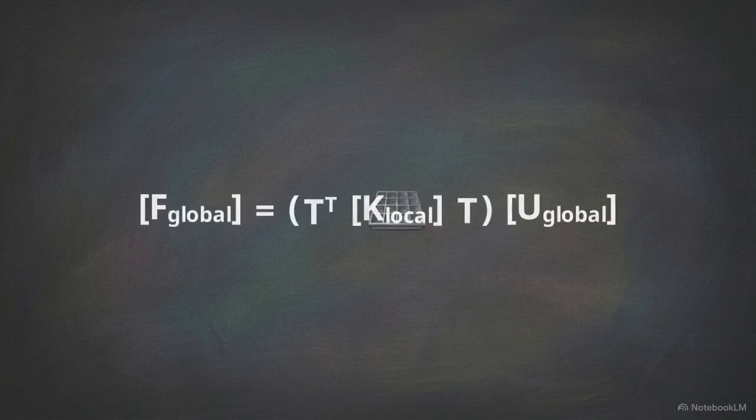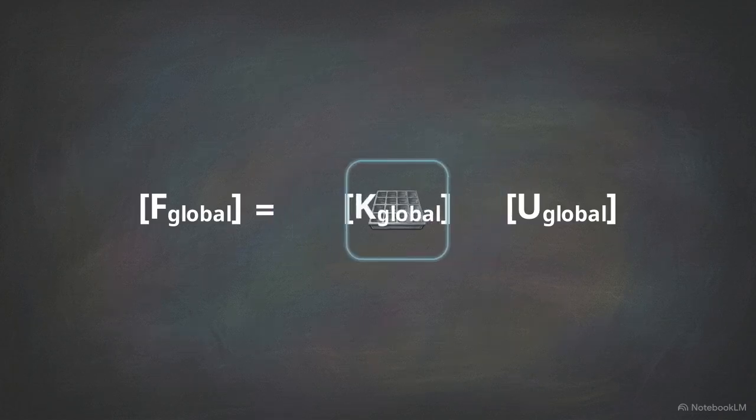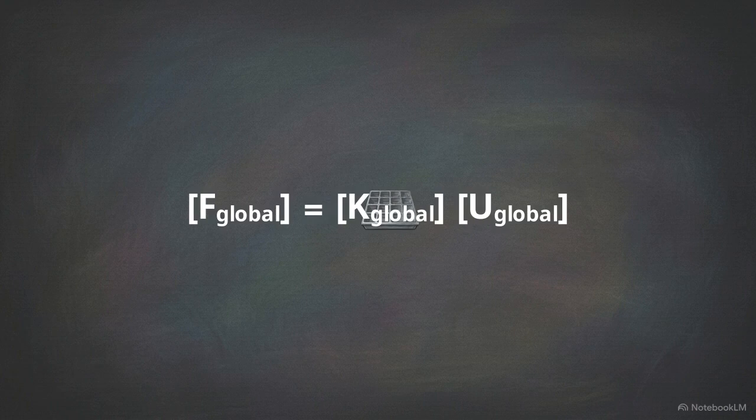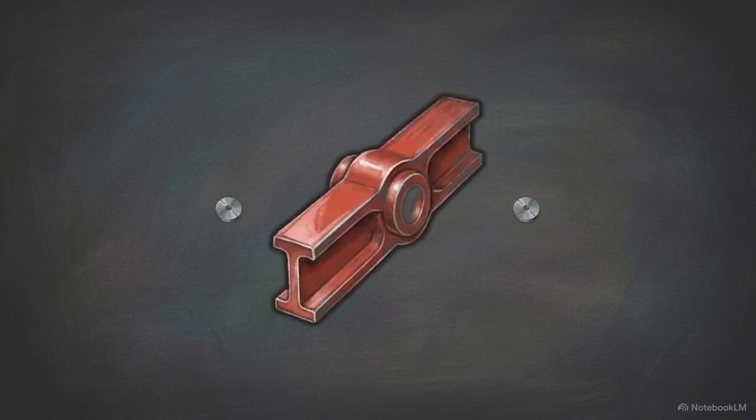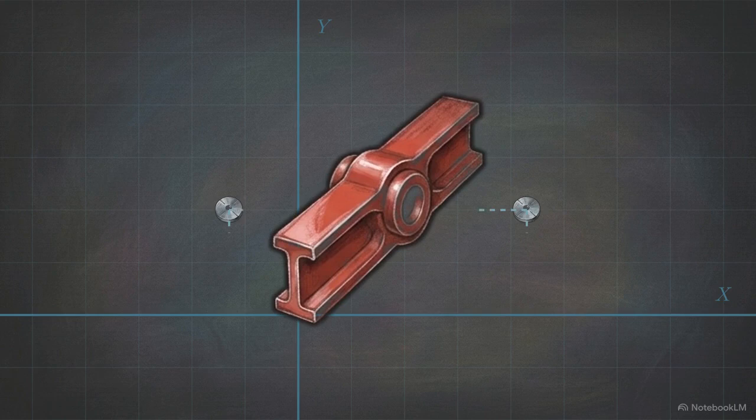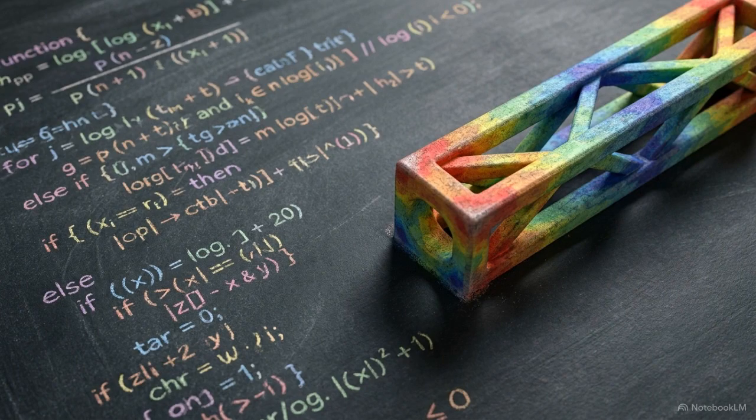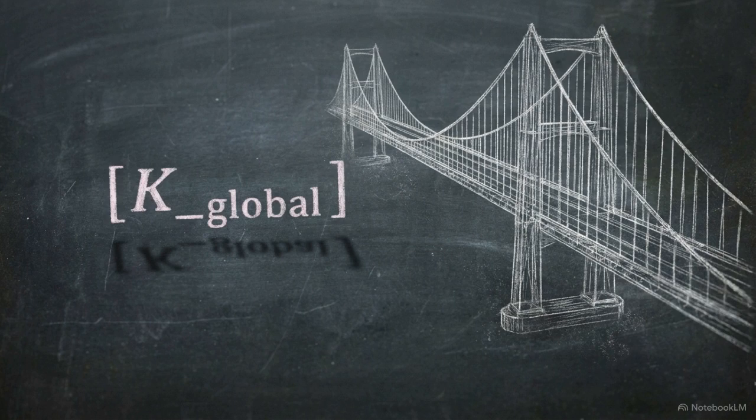In our final equation, look at this specific group of matrices on the right side. It consists of the transpose of T, the local stiffness matrix, and the original transformation matrix. This cluster is the global stiffness matrix. We have successfully translated a one-dimensional physical property into a two-dimensional spatial coordinate. This formula serves as the fundamental instruction inside every commercial finite element solver. The dimensional gap between local stiffness and global geometry is bridged by this matrix product.